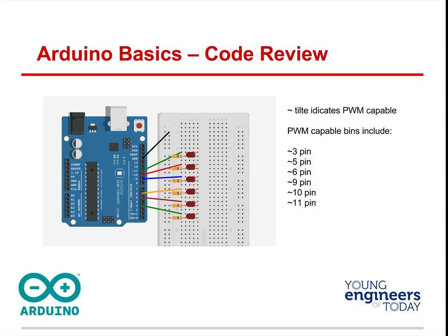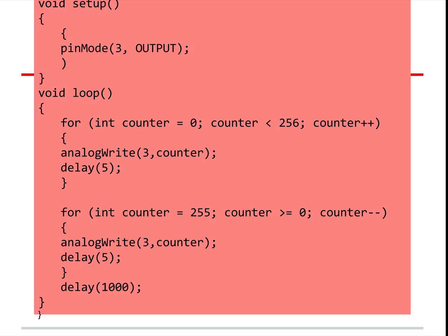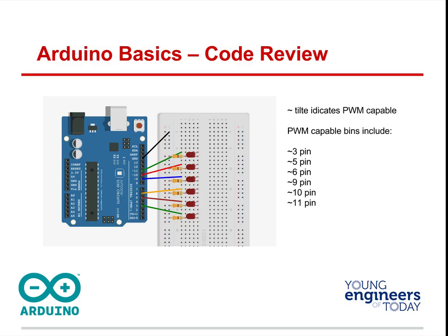All right. Now, what we're going to do next is, first of all, hook this up. You can disconnect some of your pins, what you had running, where you had all these hooked up. You're going to go from 3, 5, 6, 9, 10, 11. And then you need a ground. And then you have your LEDs connected to your resistors. Okay? Take a minute, make sure you build this.